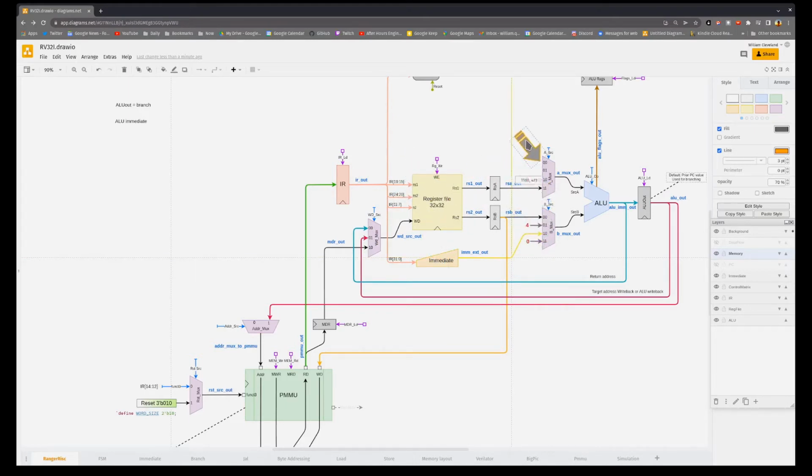That means we need to control these 2 signals and now this one. They're routed into the ALU. The address is calculated and loaded into ALU out, and then it comes around here and is presented to the memory. Now this is once the memory fetches the data out, we then route it into the memory data address register through the MUX and then into a specific register specified by the RD. So that's our task. And knowing that, we know all the signals that we need to control.